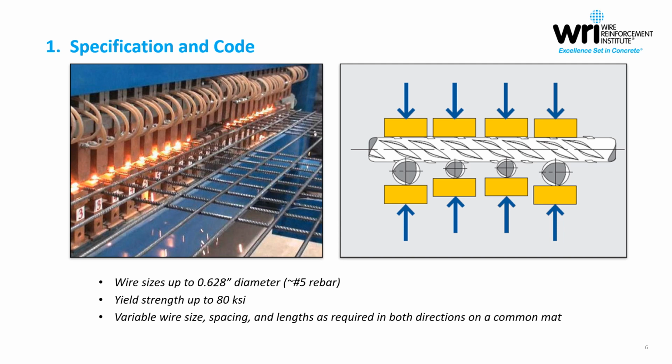Here's another view of a machine welder in action. Notice that the welding heads are programmed to selectively fire to suit the mat arrangement itself, so you can actually see those electrodes which are firing and those that aren't. The ones that aren't obviously do not have a wire intersection aligned with them.